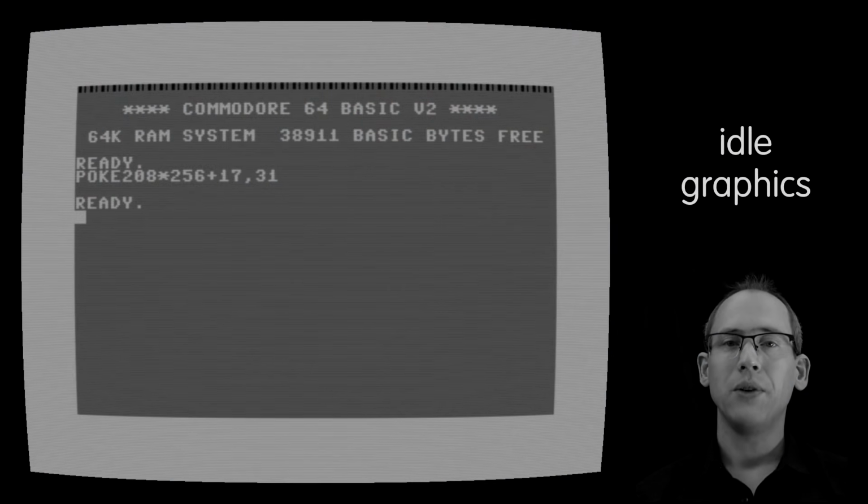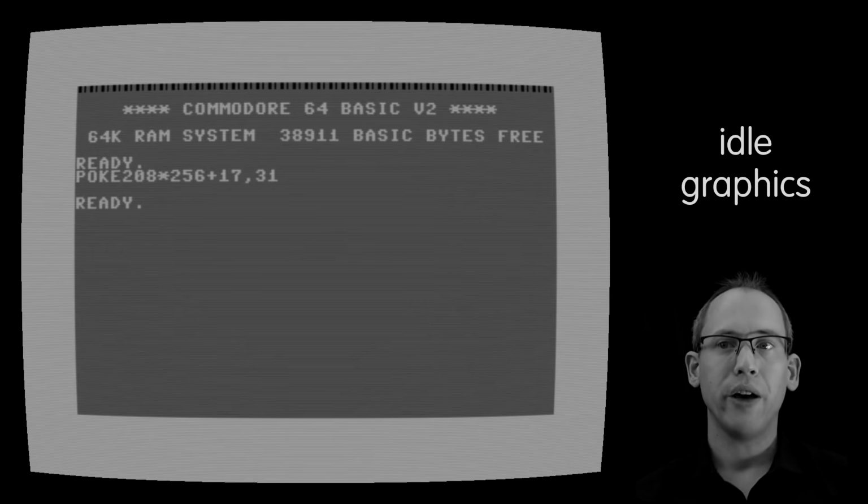Remember the idle graphics pattern, nicknamed the ghost byte. This is always the last address that the VIC chip can fetch pixels from, and that's normally address 3FFF. But ECM imposes restrictions on where pixels can be fetched from. And this actually moves the ghost byte to address 39FF. And in that location we've prepared the value FF for an all-black idle graphics pattern.